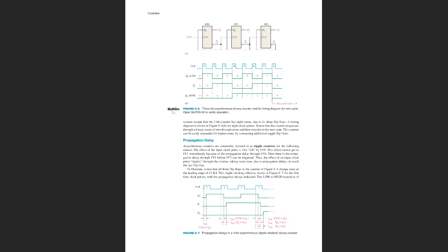Before the clock of flip-flop 1 is affected, the output of flip-flop 0 is delayed compared to the clock. So every next clock is delayed compared to the previous one. This is why the counter acts in series. Not all of them change at the same time. They act from left to right.